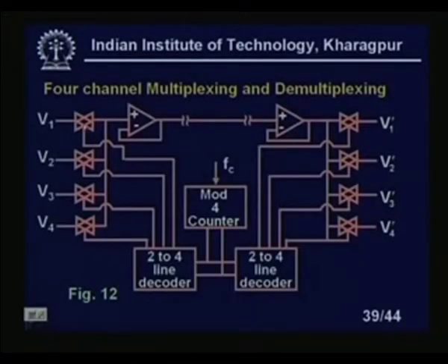What is that? You see that when I am giving the control signal to V1, which I have shown just now, even though signals are present at the input, they will not come to the output, because all the outputs are connected together. Whenever this switch is on, all other switches will be deactivated, which means those signals will not come through. Again, it is demultiplexed at the outputs. So V1 will appear as V1 dash, V2 will appear as V2 dash. So I am sort of sampling here. Similarly, when V2 is on, what will happen?